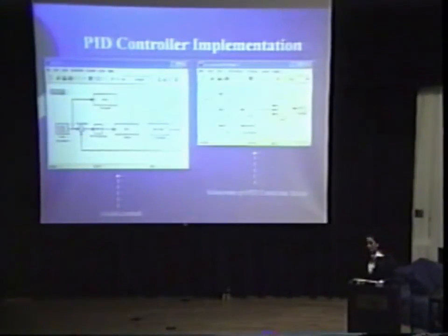To implement a PID controller, the first step was to take the model used before to control the servo system and add a PID controller block, which was already provided in Simulink. The gain block from the previous system was deleted, and the PID controller block was added in its place. This also shows the subsystem capability of Simulink.